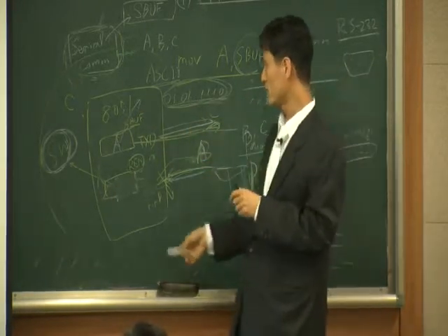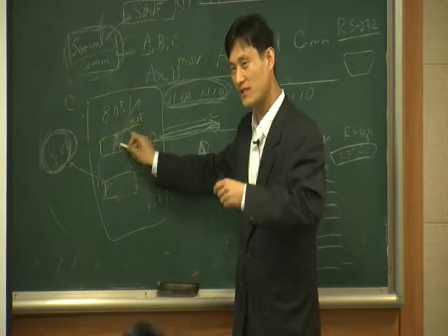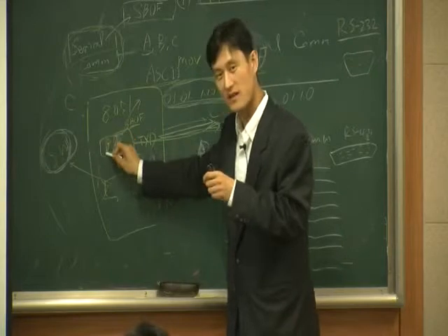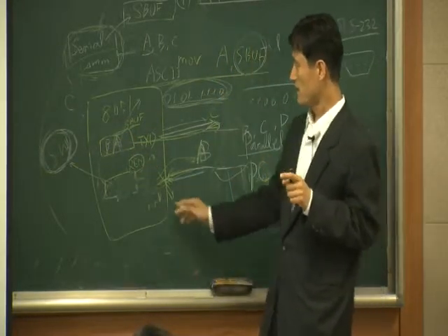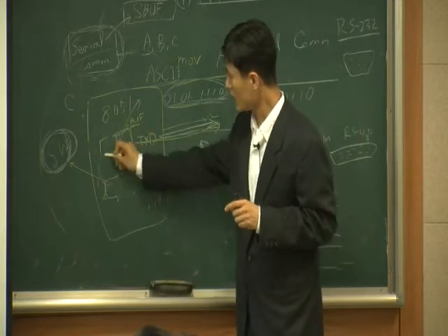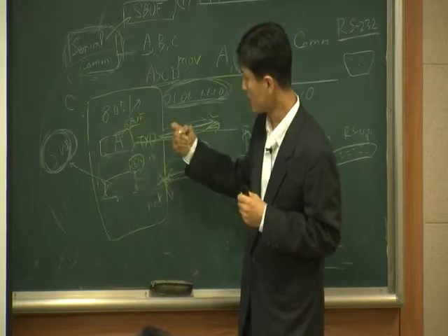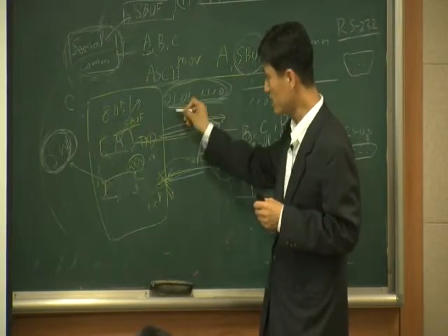So what you can do is write the value A, and immediately later you write the value B. If you do that, then when you write the value A here, the hardware will take this one and convert it to ASCII and transmit, but I didn't finish it yet.